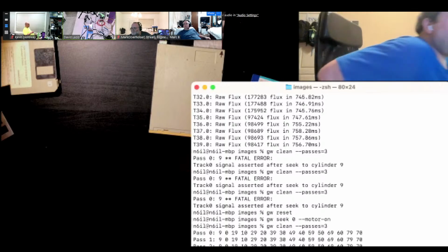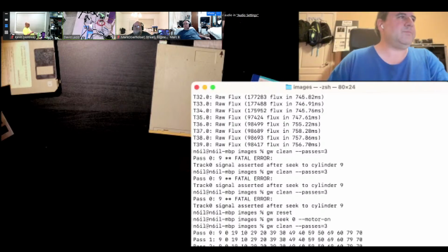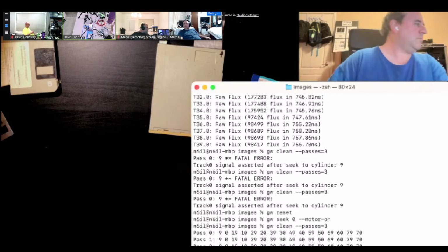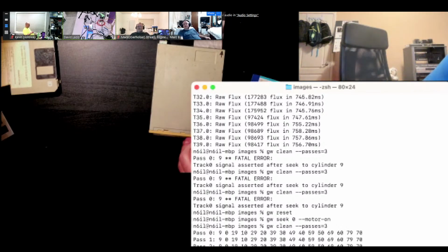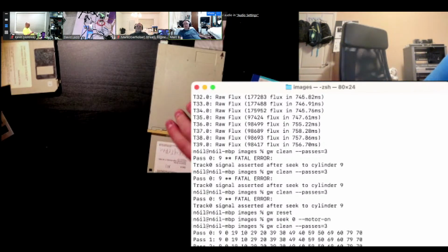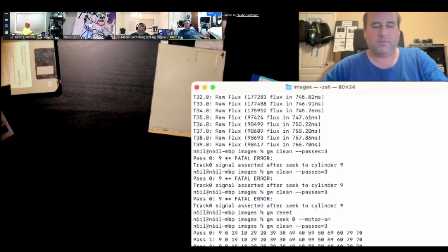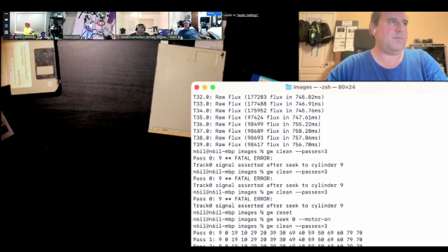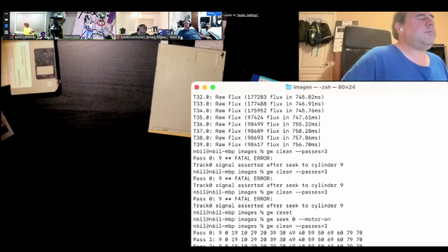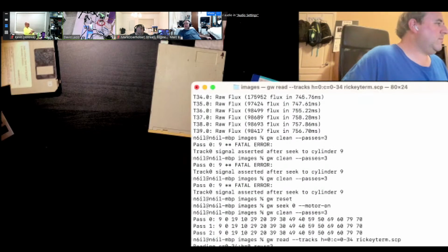It's not like FM versus MFM, where the encoding's different. It's the actual speed that is different. So, well, that switch signal goes back to the controller, and so it's telling the controller what speed to use. On the 3.5, yes. The 5.25, actually, the controller tells the 5.25 which mode to be in. Right.